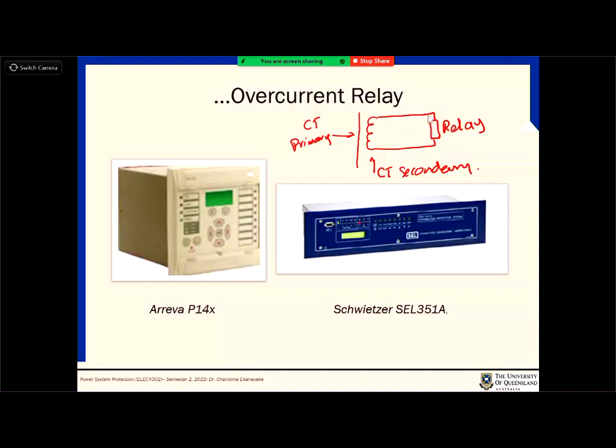So that is the maximum impedance that the CT can drive, right? At that point, the CT is not saturated. Saturated means that otherwise the flux goes into a level where it's not in the linear region. You are working in the non-linear region.